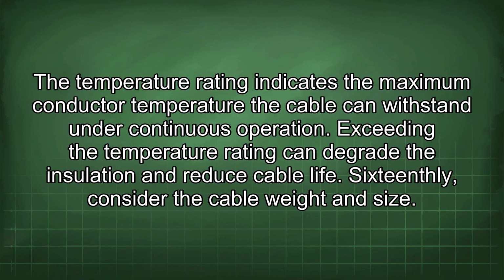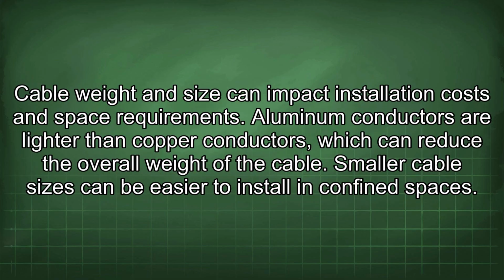16thly, consider the cable weight and size. Cable weight and size can impact installation costs and space requirements. Aluminum conductors are lighter than copper conductors, which can reduce the overall weight of the cable. Smaller cable sizes can be easier to install in confined spaces.